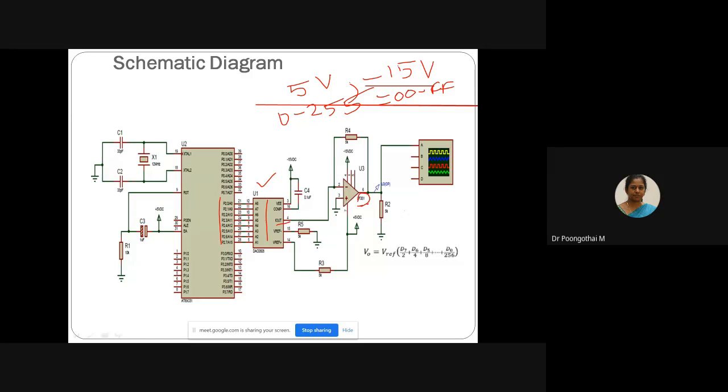For changing the current parameter to a voltage parameter, this LF351 operational amplifier is connected in the circuit. Basically, this LF351 is one kind of JFET operational amplifier. This is an inexpensive device with characteristics like high performance, a high slew rate and a high gain bandwidth, and it even operates with low power supply.